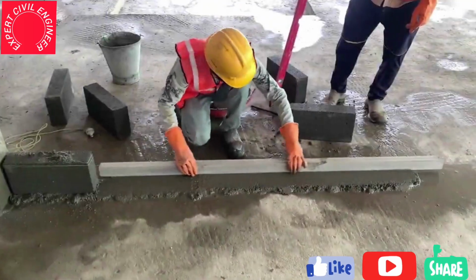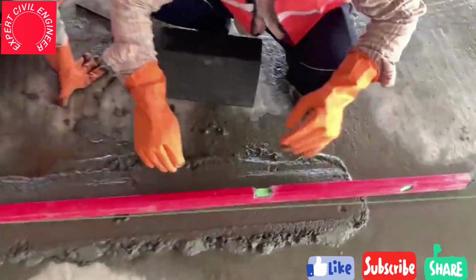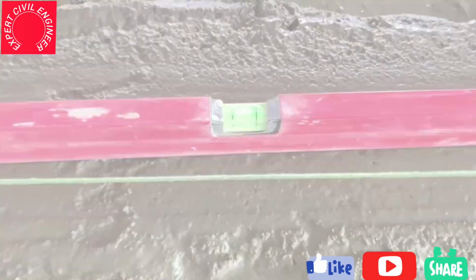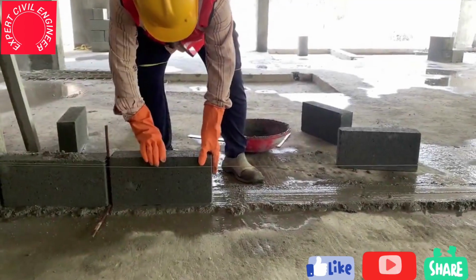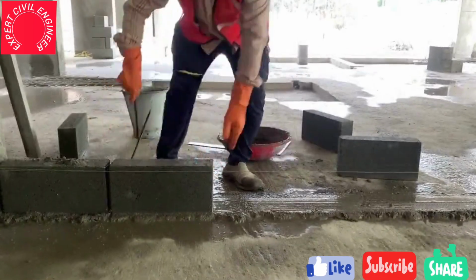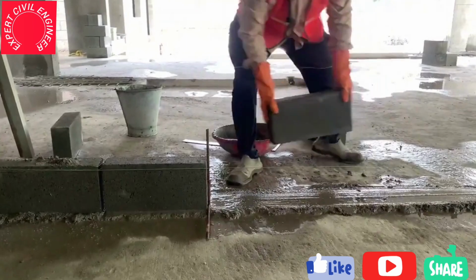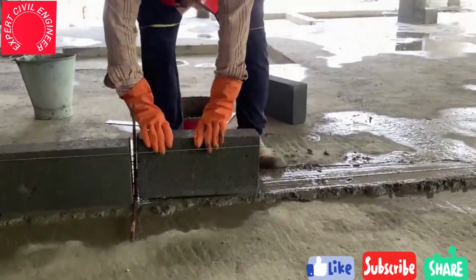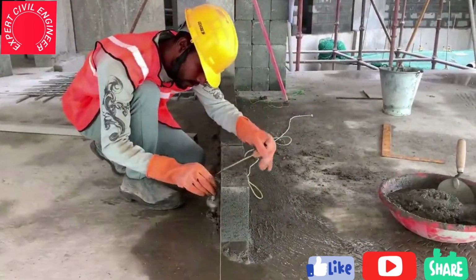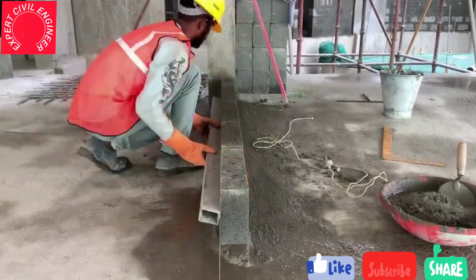The bed mortar must be leveled using an aluminum straight edge, and it is mandatory to verify the level of the bed mortar using a 2-meter spirit level. The first course of blockwork should be laid with reference to a nylon thread to ensure proper alignment, and it is essential to maintain an equal distance of 12 mm between each block. This could be done with a simple gauge tool. Immediately after laying the first course of blockwork, it is crucial to check the line and plumb by using straight edge and plumb.